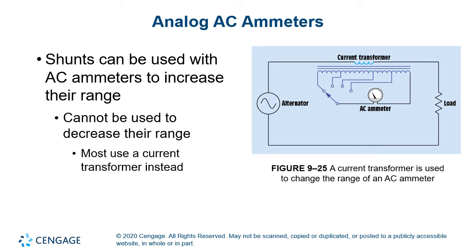So let's take a brief amount of time and talk a little bit about analog AC meters. This is for alternating current. Keep in mind, we can't just use a simple needle, right? The needle is actually measuring current. It uses an internal magnet to move that around, because alternating current is essentially going positive, negative, positive, negative. Anytime you connect alternating current to a DC meter, you will very likely get a zero reading. Essentially it just cancels out.